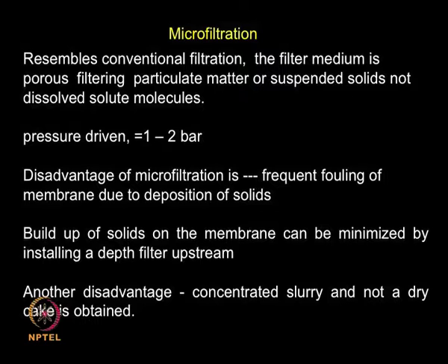So buildup of solids on the membrane, how do you minimize it? We can have depth filters upstream or a normal conventional filter upstream. So it will capture all bigger particles, and then you go to the microfiltration, and then you resort to further filtration. Another disadvantage of microfiltration, because the pressures are not very high, you are going to get a concentrated slurry. You will not get dry solids after filtration.